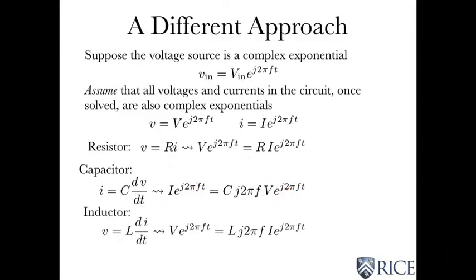And I'm pretty sure you can believe that for the inductor, a similar kind of thing is going to happen. Amplitudes are related by a different formula, but still they're related. Okay, this cancellation is really important because let's think about defining a quantity Z for each element that is the ratio of the complex amplitude of the voltage divided by the complex amplitude of the current. This is known as impedance.